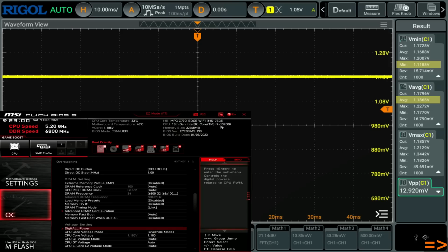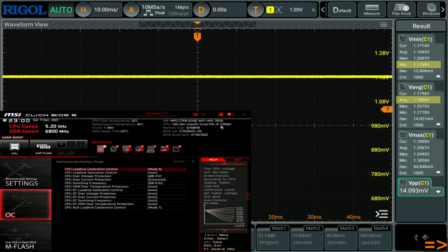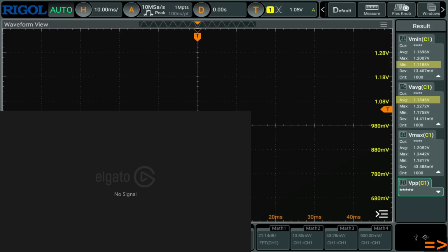There are some high-end motherboards that have a circuit to replicate the DieSense reading over to the Super I/O, but when I say high-end motherboards, I mean boards north of $500. You don't really see that functionality on anything else. Anyway, so next we're going to go to 1.22 volts and mode 5 LLC. Which is still going to have terrible voltage regulation, but it's going to be significantly less terrible than what we just saw. What was it, like 110 millivolts of undershoot, which